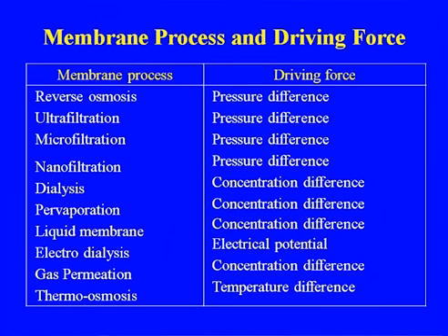Dialysis is the concentration difference, evaporation concentration difference, liquid membrane concentration difference. Electrodialysis, the electrical potential is the driving force, and gas permeation, concentration difference. Thermoosmosis, the temperature difference is the driving force. So these are the various types of membrane separation processes which we are using in some form or other in the chemical industry.